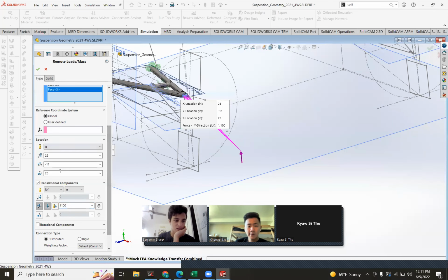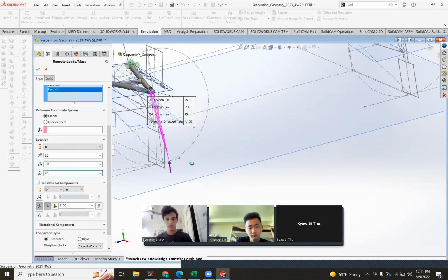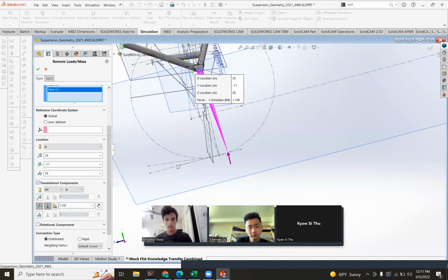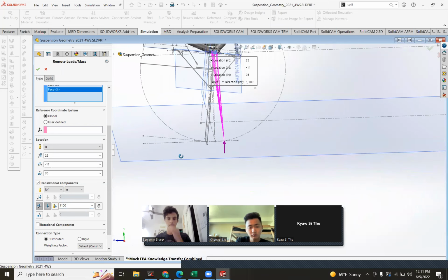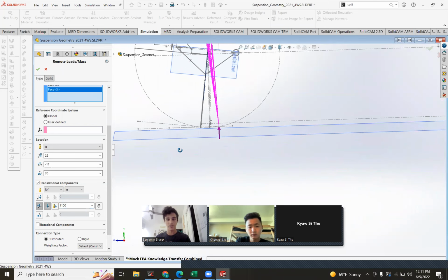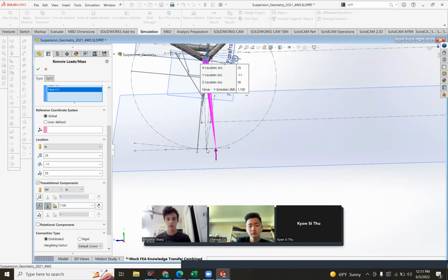We did all right. It's kind of close. We're going to make Z 30. No, we're going to make Z 35. Remember, it's the bottom of the tire where it hits the ground, not relative to the caster angle. So it's actually this point that we're going for, not this one, because this is castered.